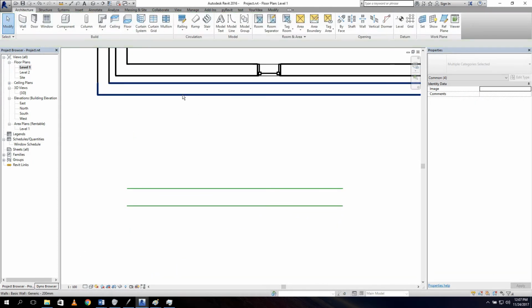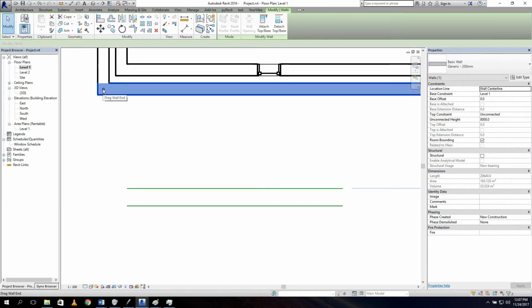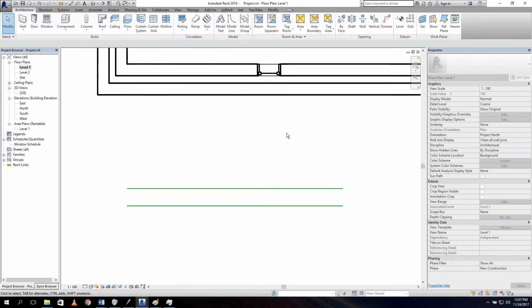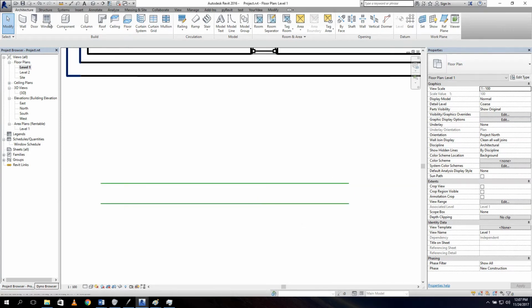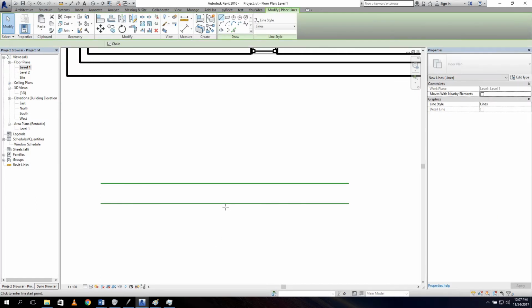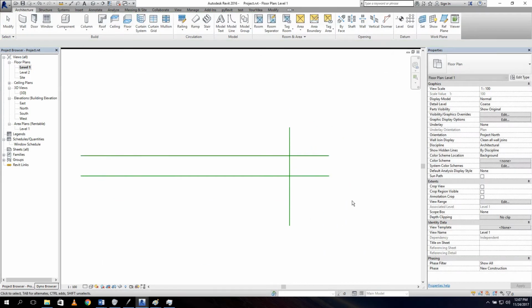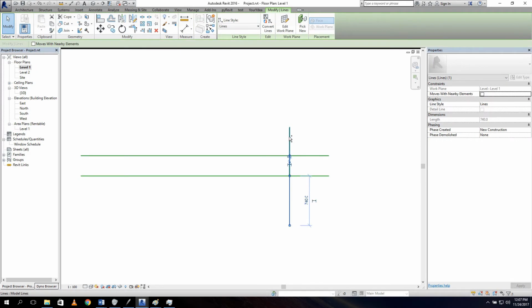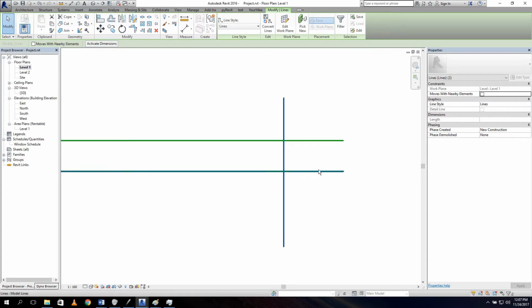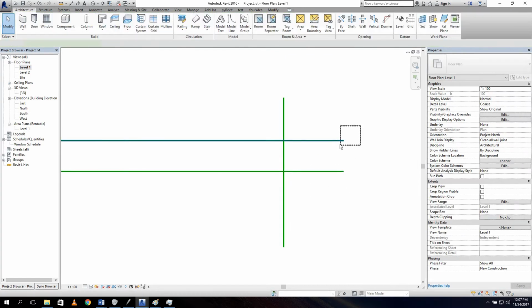And if I select those walls, normally, you can see here's my start point. This is my end point. And this is in the middle of the wall. So that's representing those two lines. We need to create in Dynamo those two lines. And then we need to create another line. And that line should be from any point on your wall line, go up and go down like this. And then we're gonna make a test if this whole line actually, like so, intersects with this line and with the upper line. It means those two walls need to be joined together.